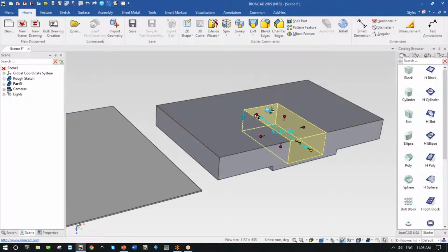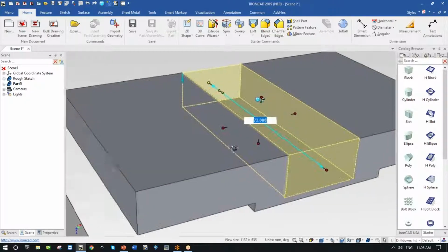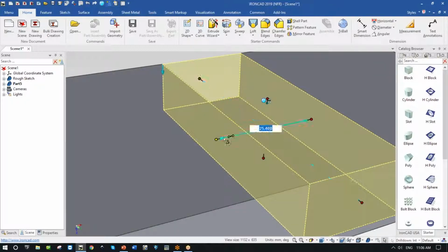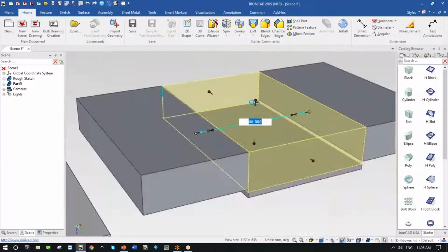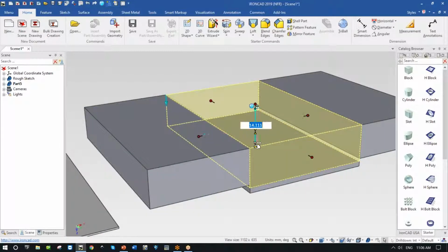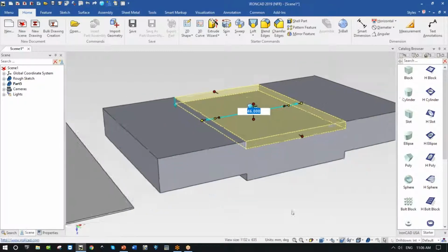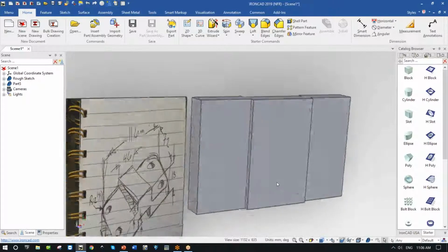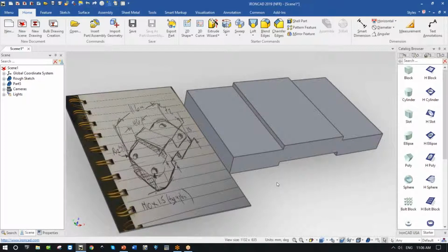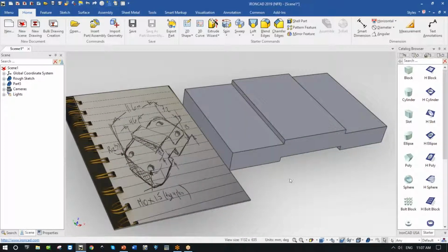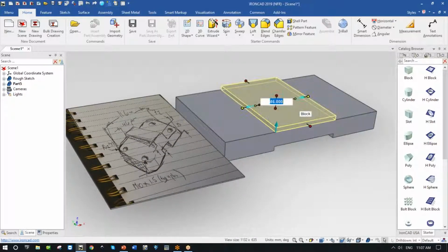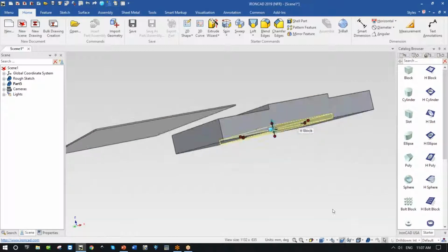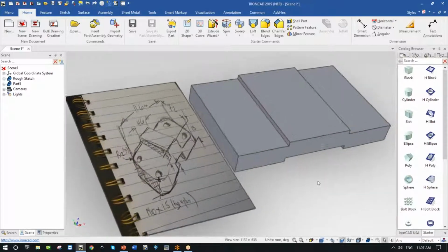Shift, grab the front, find this back face. And then as I zoom in to see, well, how wide should this be? Oh, this should be equidistant, 46. How deep? Well, we had said it should be exactly 3 millimeters deep. There you go. So I'm creating this part without having to do any sketching at all. I used a positive part on the top and a negative shape on the bottom.